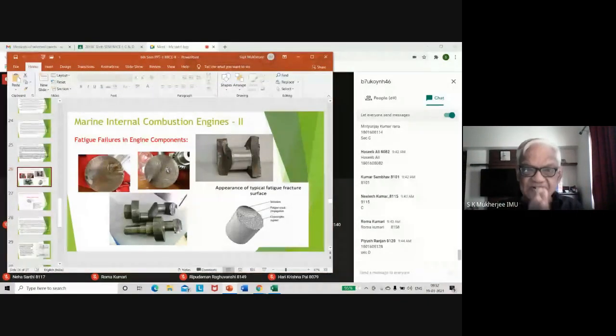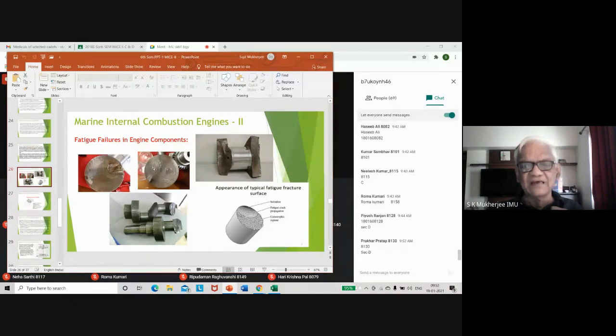So the separation of the surface has been expanding separately in all directions till the one closest to the circumference has reached the limit. But on the other side, the crack continued till such time there was not enough material to support the resistance, and then the entire shaft has fractured. So not all shafts fail from the surface.